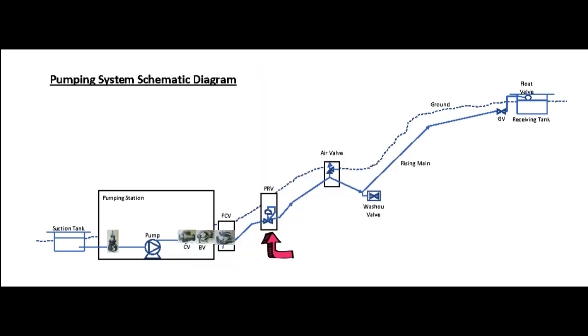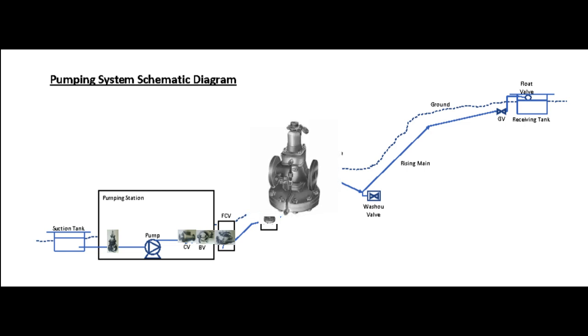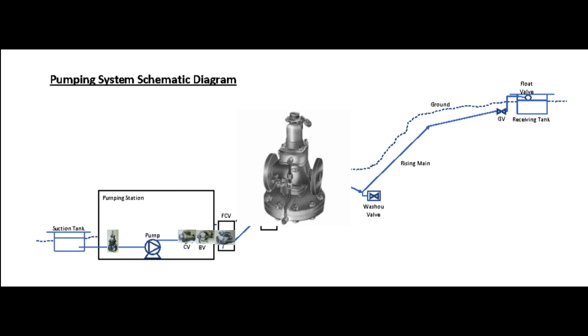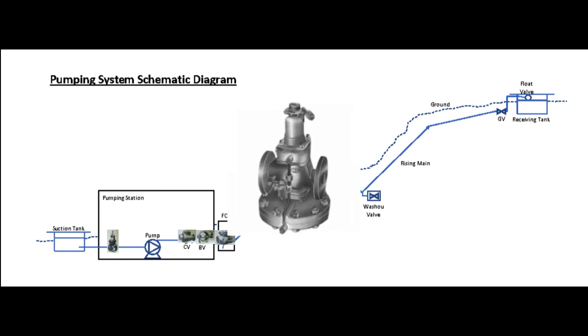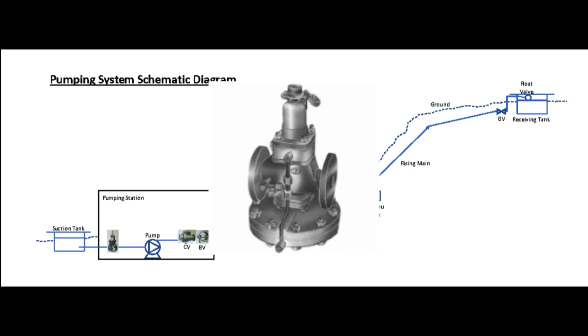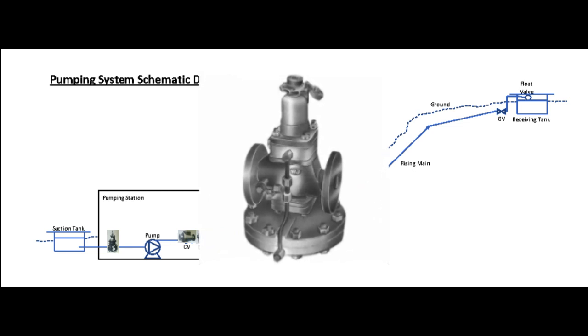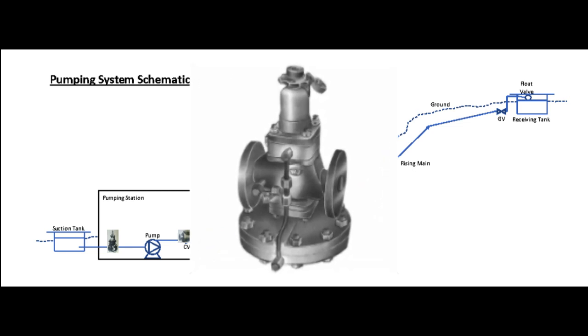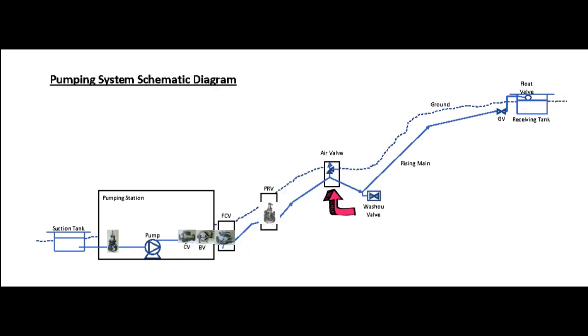Pressure reducing valve. This valve is installed at the pumping station or rising main where the system pressure needs to be set at a pressure which is lower than the pump operating pressure. Pressure reduction can normally be achieved with 1/3 of the system pressure. With higher pressure reduction, careful selection is required, such as step reduction or providing a cavitation trim to avoid any cavitation and vibration.